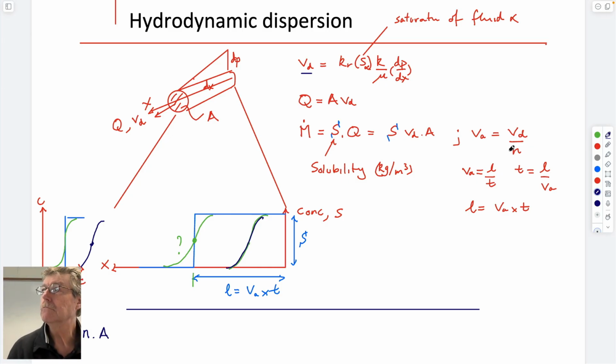A different way I thought about it was, in the sense that it is the same number either way, because the flow is V times area. If you're using the advective velocity, you're going to use the open area, and the open area comes back to be the same. The velocity is divided by porosity, so that cancels out the same. Yes. I just wanted to check that. Okay, I'm fine with that.